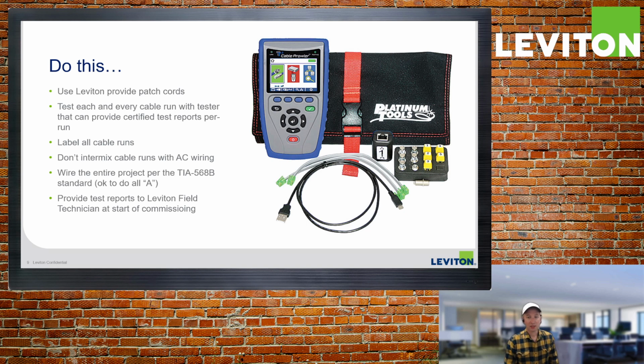Do this. Next, don't intermix data cable runs with AC wiring. It's an NEC violation and your system won't work well, so don't do it.